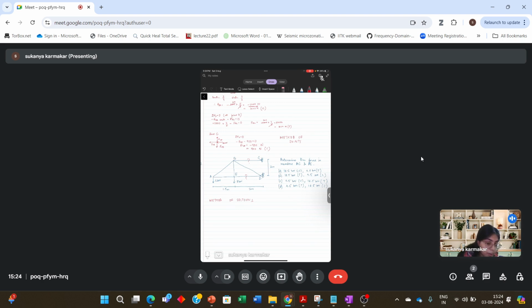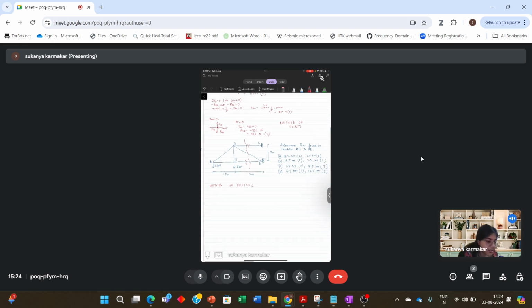These two forces in the members have to be calculated, BC and DE. So let's cut a section like this, and let's take the left hand side of the truss. This is force in the member BC, the force in the member BD, force in the member ED.